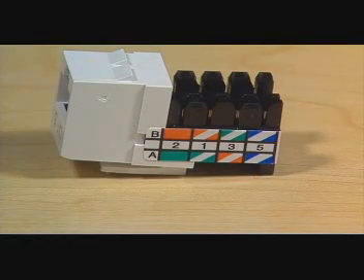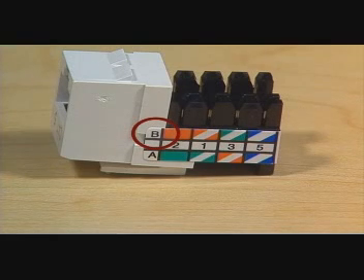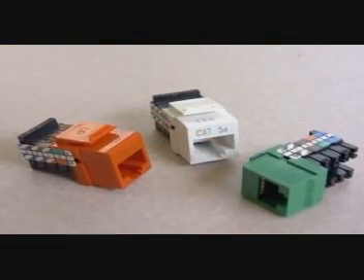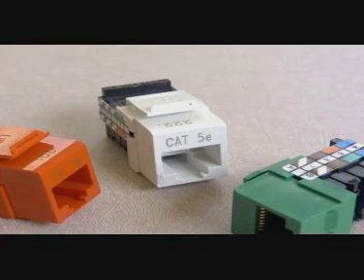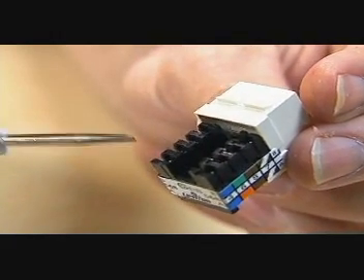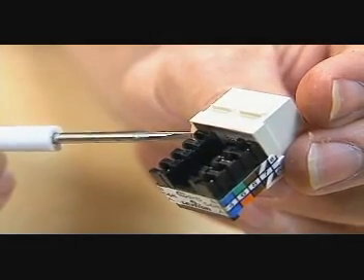Now, it's used in some commercial installations, and you'll see it on some jack labeling, usually just with the letter B. You must use plugs and jacks that are able to maintain the category rating of the cable being used. Nearly all plugs and jacks you buy are rated for Category 5 service and use these insulation displacement contacts.